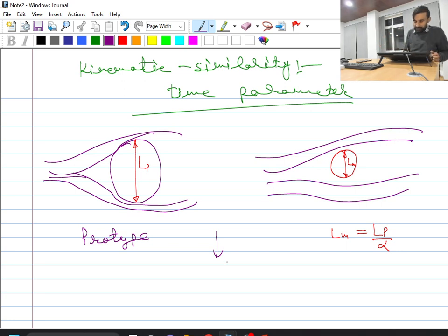You will easily recognize the Reynolds number. But once we have said that the flow is inviscid, the effect of Reynolds number has vanished. We need not consider it because viscosity is not playing any role. So in this situation I don't have any dimensionless parameter which is dominating other than just the scaling of length parameters.